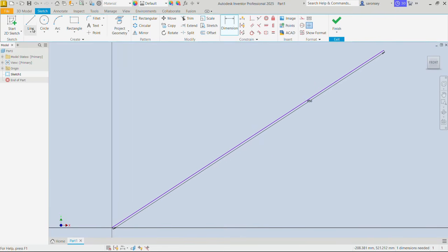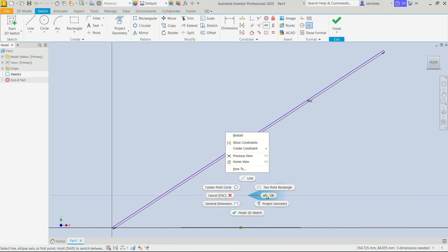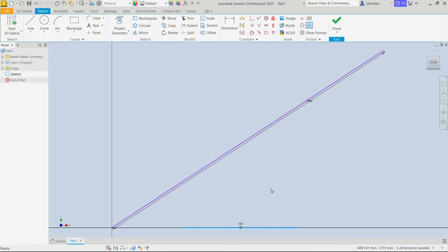Okay, you can zoom in or double click your scroll mouse button so you can get your work in focus. Let's pick the line command. Let's draw a horizontal line here. You can right click OK. We want to align horizontally the midpoint of this line with the origin. You can right click and then OK also. For this line, let's make it constructional. Now we will dimension the distance between the slanted line we drew and the horizontal line as 45.